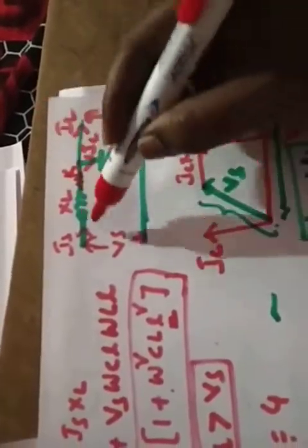So what is VS? VS is nothing but IS R plus IS XL. Whatever IS is, it is equal to IC, so IC into R, which is parallel to the current, and IC into XL. Nothing else is there. You just consider this as VR. So you need to neglect IC, XC and all the other components. What you have to take as the reference vector is VR, and the current is IC.